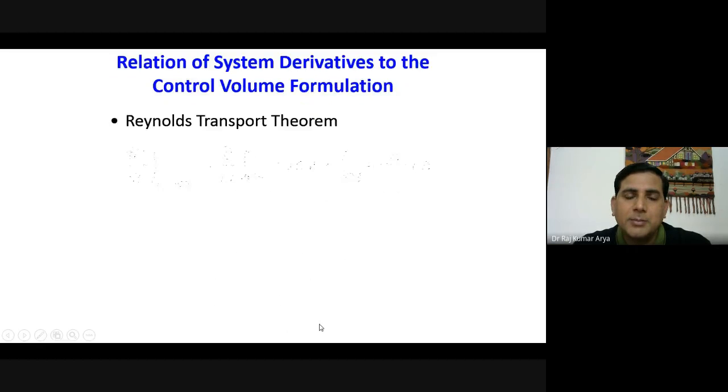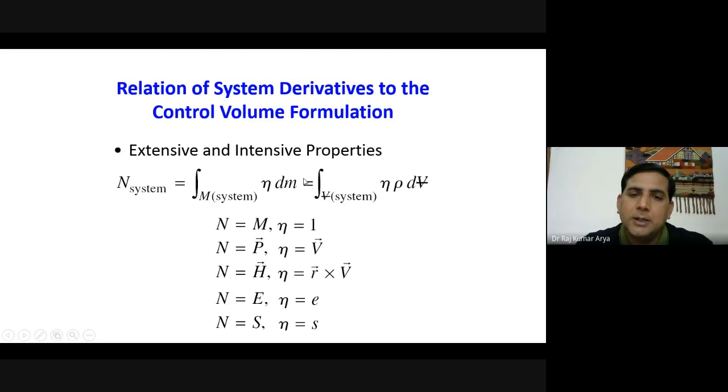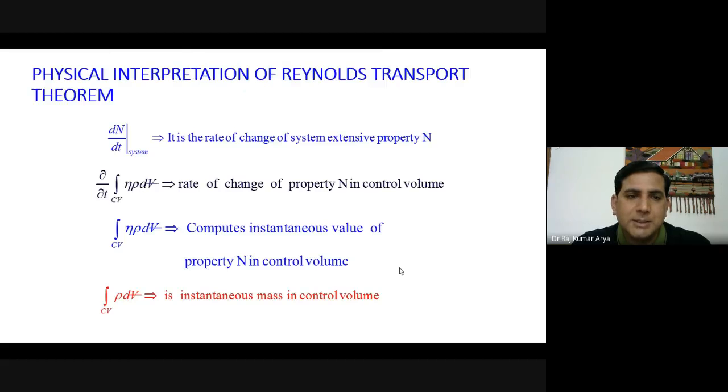So this part we did. This was the Reynolds transport theorem, which you have used to divide the system approach into the control volume and control surface. Here this eta would change according to this slide, and you can write all these fundamental laws. Based on that, you have to simplify what is to be done or not, right? So this was the case for these fundamental laws.